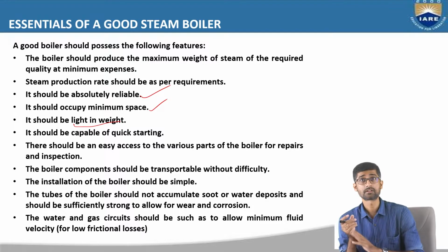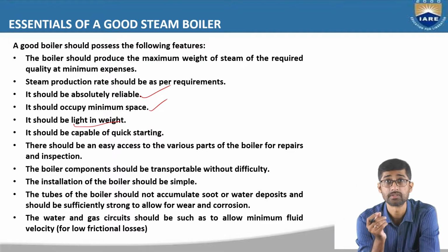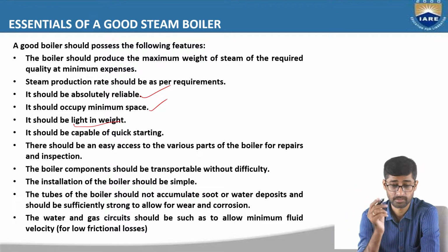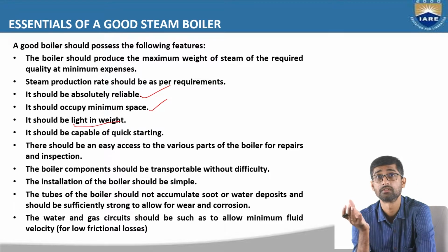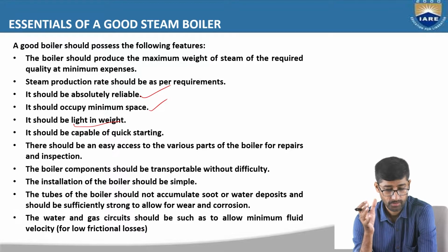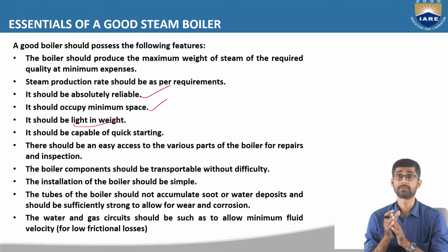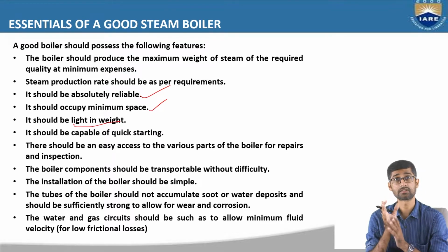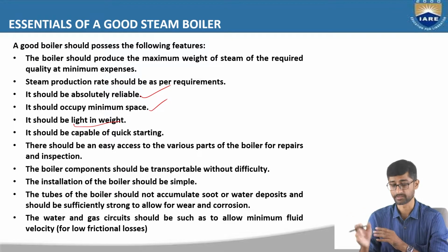The boiler components should be transportable without difficulty, and the installation of the steam boiler should be very simple. That also we are going to see when we are purchasing a boiler. The tubes of the boiler should not accumulate soot or water deposits and should be sufficiently strong to allow for wear and corrosion. The water and gas circuits should be such as to allow minimum fluid velocities for minimum friction losses.